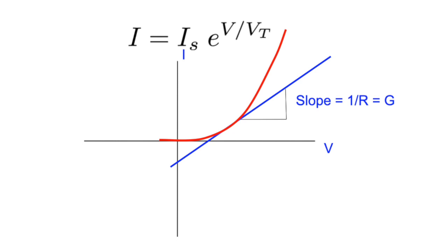And so we can look at that curve, that red curve, and say, okay, what does that tell us? It tells us that it's not a linear function, or at least not linear throughout. Remember, we looked at functions before and we said this is piecewise linear. Here, the bottom is piecewise one part, and then further along as you go to the right with voltage, there's another part that is piecewise linear, and in between is this exponential transition.